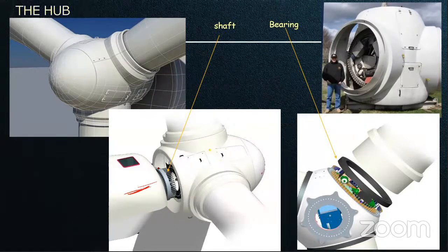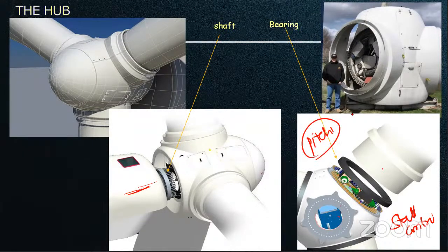In some turbine technology, the blades are firmly fixed on bearings, the bearing which connects the blade and hub. In some technology there will not be a bearing. The machine whose blades do not have a bearing is called a stall controlled machine. The machine whose blades connect to the hub through bearings is called a pitch bearing machine, where pitching will happen.